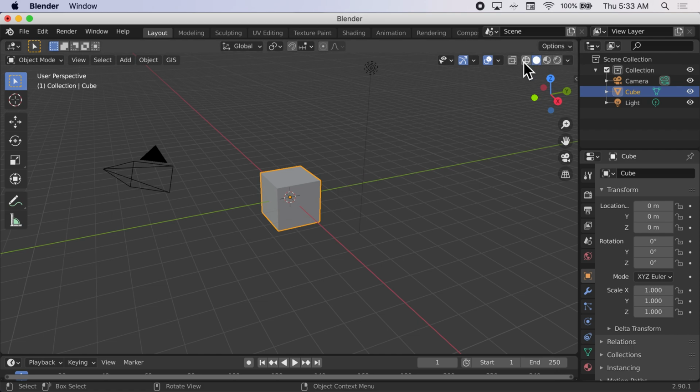The next thing I'm going to do is point out some things about the top right area here where these circles are. These are little pictures of spheres. This is a view where you can actually see through. It's like an X-ray mode. And this allows you to select things that are behind faces. So this particular cube, you normally would not be able to see that back corner point or vertex, but if you put it in another mode, like shaded mode right here, then you cannot see that back corner of the cube. So that's important to point out, that sometimes it's useful to go into this X-ray mode whenever you want to maybe drag a box around something and select all of the parts of the thing that are behind different faces.